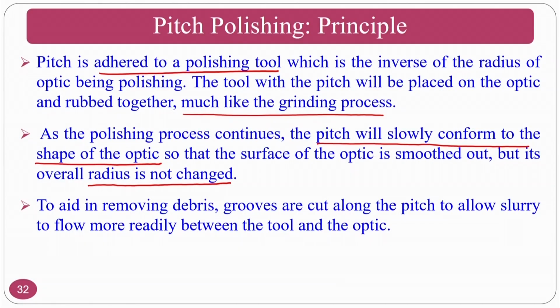And to avoid removing debris, grooves are cut along the pitch to allow the slurry to flow more radially between them. Normally you can give some scratches on this pitch. Normally if you see, the polishing tool will be like this, wherein pitch will be there.